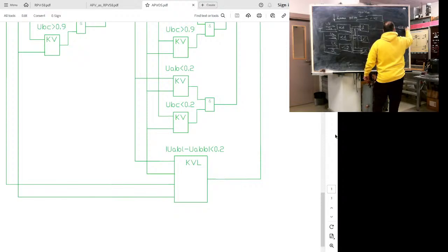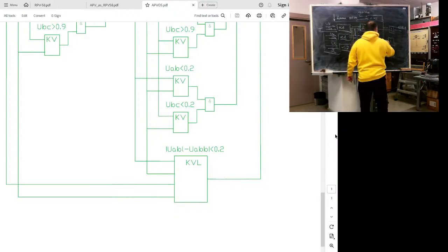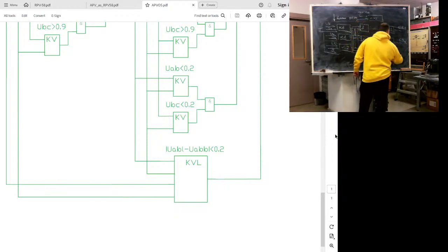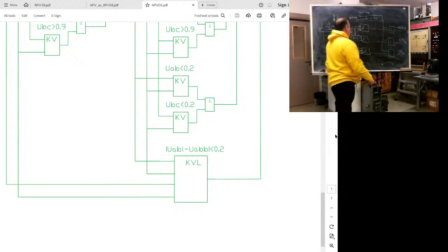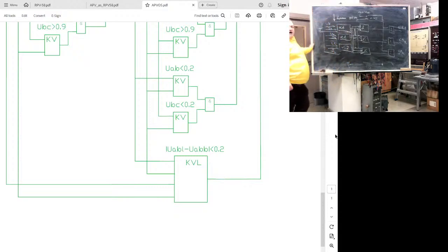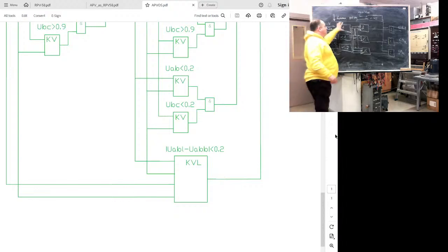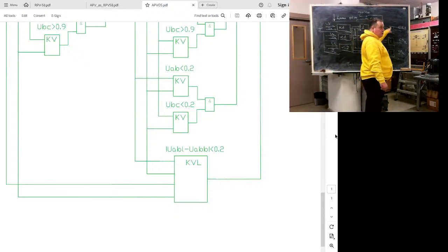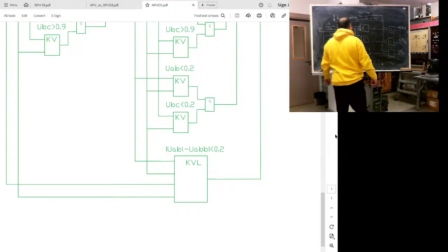okay, CBA, CB for B phase, CB for C phase. In case of only one phase, this has its own set of phase selectors. They are distance relays designed to produce 1 only if the fault is on their own phase. So if the A phase selector triggers, it gives us 1, B and C 0, and only in this way we will have 1 here. From the logic will come a signal to it, and for CBA a signal will appear.